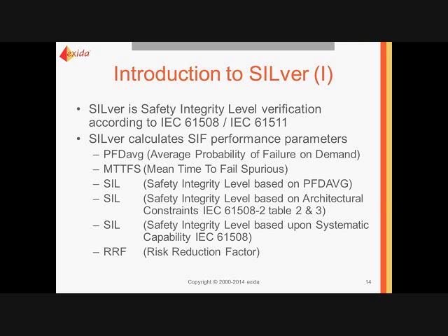So if you've not used a quantitative methodology for determining a SIL, then you need to add another safety margin, which is better to say instead of SIL 1, you'd say SIL 2. Because if you don't put the risk reduction factor in, you said SIL 2, then the designers would probably design you a SIF that was closer to 100, which would give you a safety margin on top of your risk reduction factor of 65, if that's what it turned out to be.